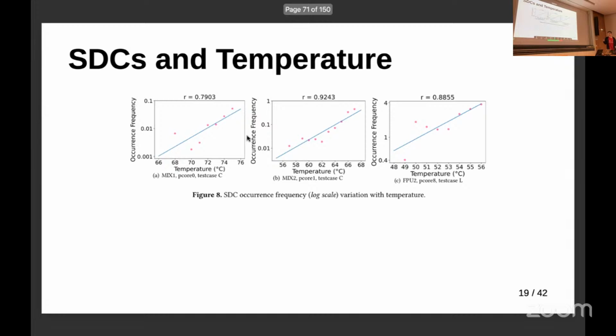This helps explain a number of issues that had seemed inexplicable at first, yet later turned out to be temperature related. For instance, in one case, they found that other cores being busy increased the rate of a particular core causing silent data corruptions. The more cores that were busy, the more that one core had errors. This eventually turned out to be simply the other cores being busy causing the CPU's overall temperature to increase.